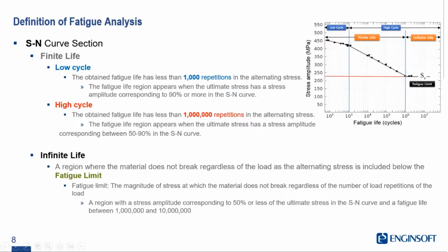For the folks that either noticed this or remember this from college, there's this infinite life or a fatigue limit. You can see that this curve is steadily dropping down. As we decrease the oscillating stress, the part will last longer, and then at some point this curve levels out, depending on the material. Some materials don't have a fatigue limit, but for example with steel, if you have a loading below some limit, then it'll never fail, at least assuming there's no defects.